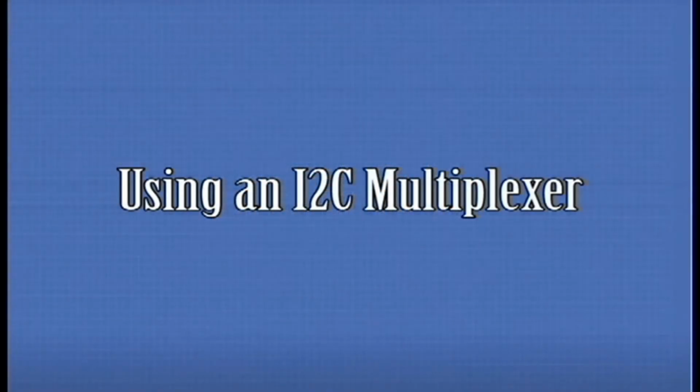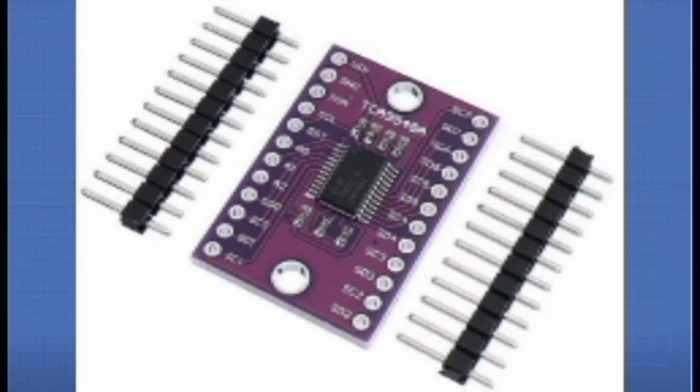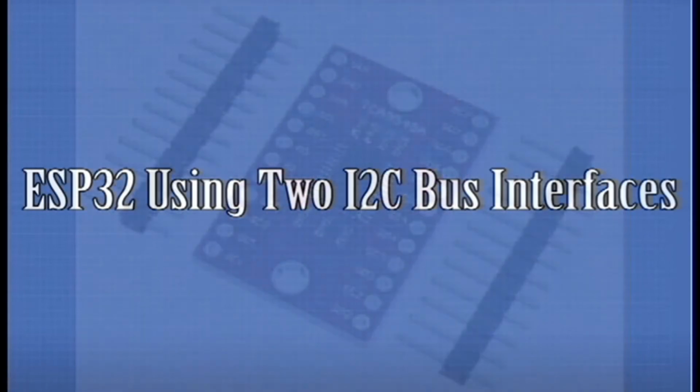Using an I2C multiplexer. However, in this previous example, this only allows you to have two I2C displays on the same bus, one with a 0x3C address and another with a 0x3D address. Additionally, sometimes it is not trivial changing the I2C address. So, to have multiple devices with the same address on the same I2C bus, you can use an I2C multiplexer like the TCA9548A that allows you to communicate with up to 8 devices with the same address.